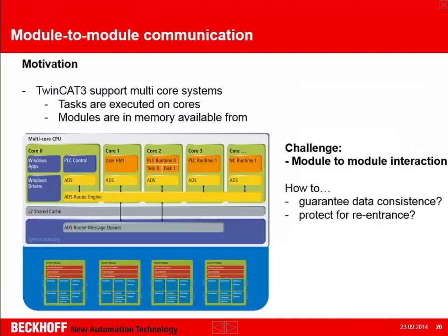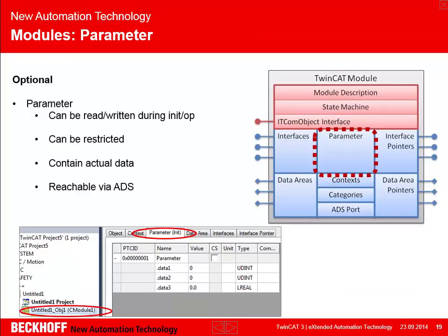So in case you want to do startup parameters, that's also easy to provide. There's a mechanism called parameter as its own category, and you also define it in the TMC editor, pretty easy. But then this is not available to be mapped to physical input outputs.